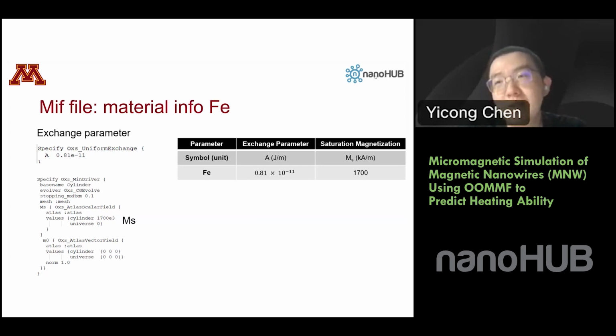Well, it will be better to have a smaller mesh size for the simulation, because the finer the better the results, right? But sometimes this will sacrifice simulation time, so you need to find the balance between these two. If you want a really good simulation, you would use a very small mesh size. But if you just want to find out the general property of the particle, you can choose a larger mesh size.